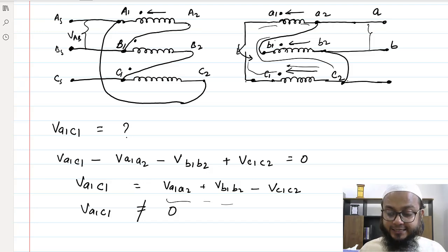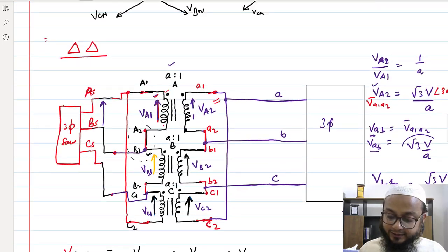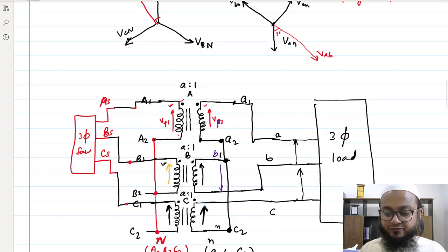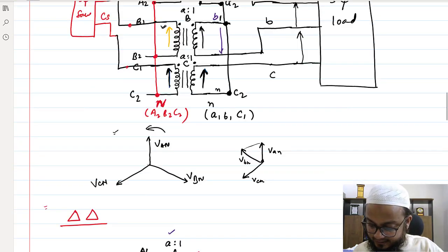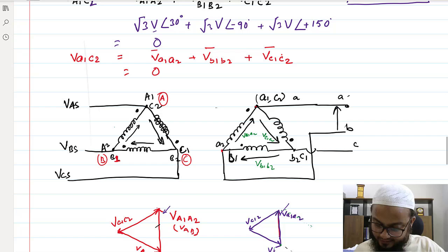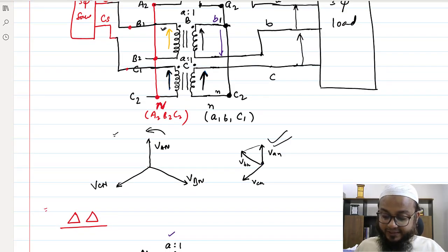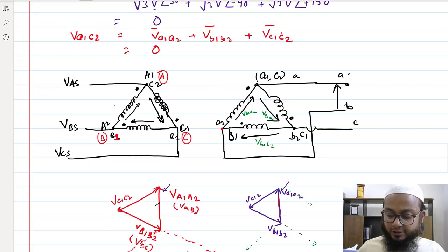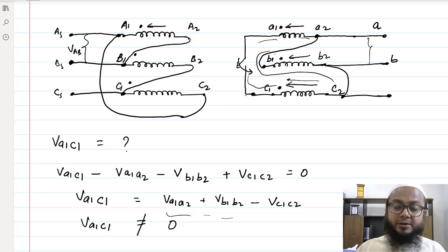So in a star connection, if someone had made a mistake in connection, he will still get a voltage, but the line voltage would be reduced and an unbalanced voltage supply would be there. That's what we discussed. But in delta connection, one has to ensure the dot connection, otherwise the chances of creating a dead fault or short circuit fault would be there.